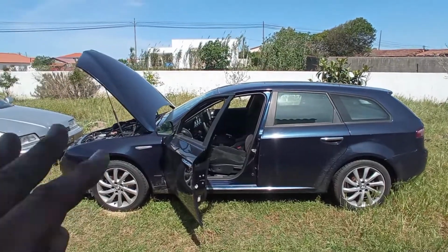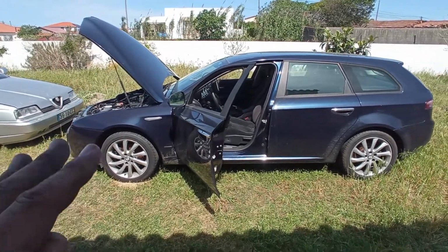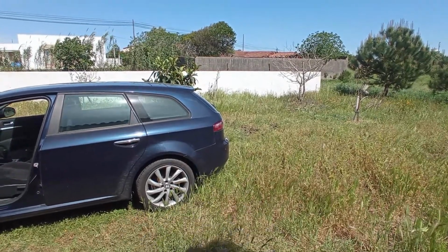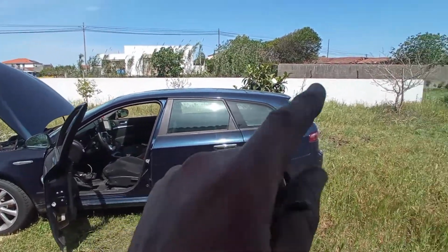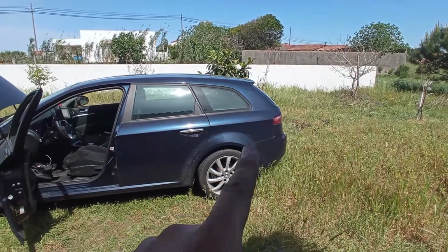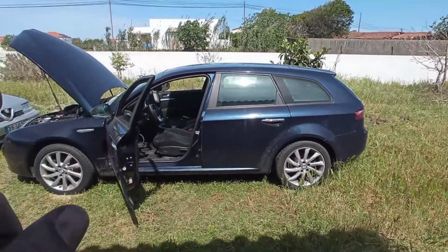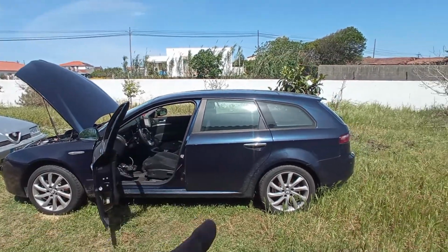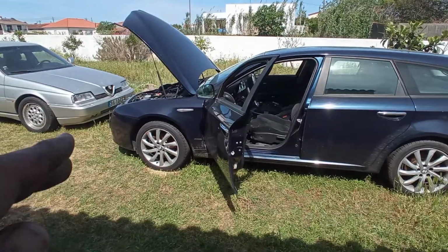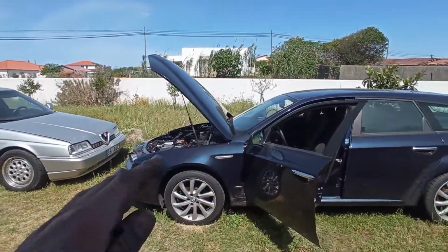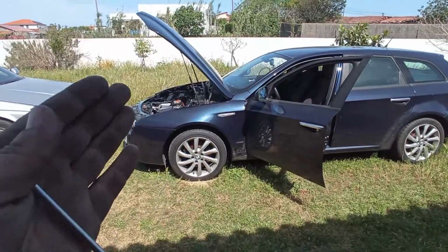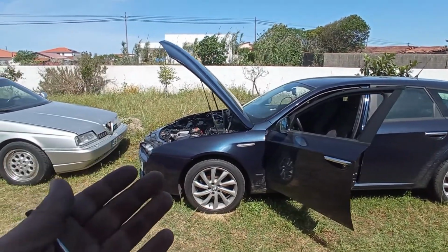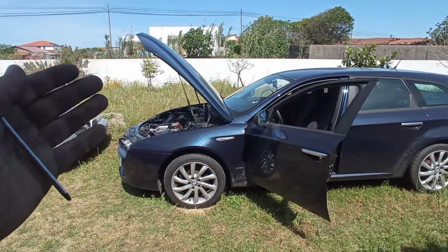One thing that is very misunderstood on the cars that do the regenerations is that once you see smoke out of the exhaust, it means that it's doing a regen. That is true, but that cannot happen. The thing is, while it's doing a regen, the exhaust is now burning something that is not supposed to be there. Like I told you, on the 1.3 liter multi-jet engines, we have the problem of the piston rings where the engine does a lot of blow-by, and now you have a lot of oil on the exhaust line.